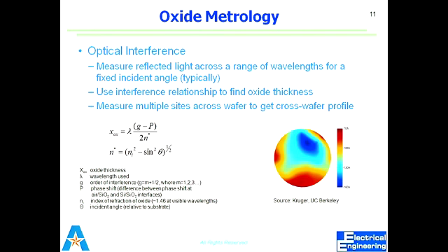The measurement of the thickness of oxide is very important, as you know that if I want to etch, or if I want to pattern the silicon dioxide, I should know about the etch rate and the thickness of the oxide. Exactly what is the thickness of the oxide until I have an etch stop, and exactly what is the etch rate of that etchant.